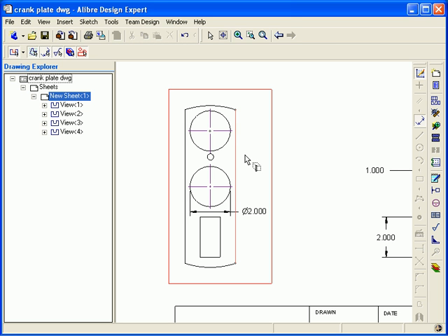In many cases, the projected design dimensions from the part may not be adequate to fully specify a drawing view. If this is the case, you can always add additional dimensions manually. To do this, select the Dimension tool from the Sketching toolbar, and then you can apply dimensions in the exact same manner as if you were in sketch mode in a part file.